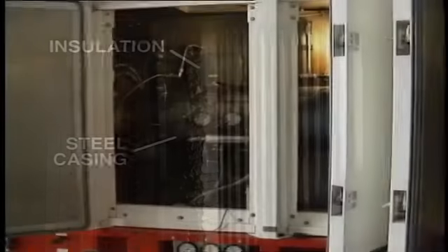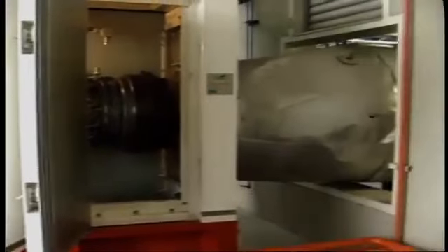The HRSG also works under positive pressure from the gas turbine or diesel engine exhaust. The tube banks must be designed to provide the least resistance possible to the flow of gas. Otherwise, back pressure on the turbine or diesel engine exhaust will reduce the efficiency of these components.